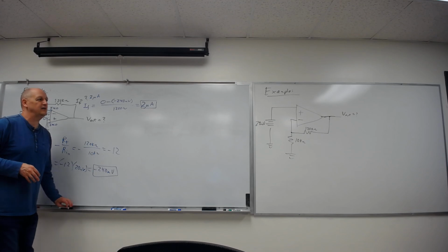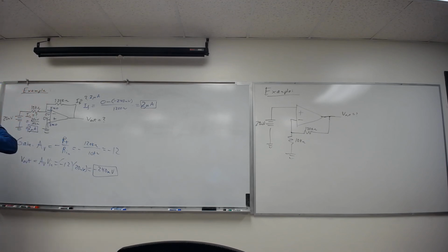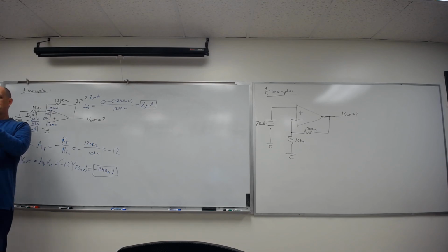That gives negative feedback, which means it helps constrain the gain. Again, what we want in the electronic world for almost everything is negative feedback. Because that means as the output gets bigger, we reduce the input so we constrain the gain. As the output gets smaller, we pull off of that so it lets the gain increase. So we're hoping to constrain that gain, which does two things. The one doesn't let it go way out of control.